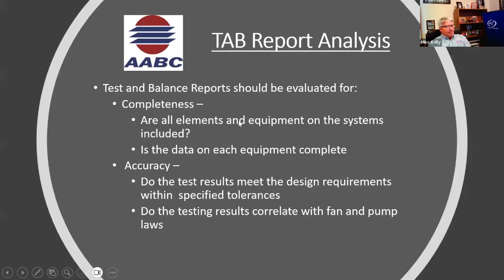All elements and equipment on the systems included. Is the data on each equipment complete? Test and balance reports should all be evaluated. Can you establish accuracy within a report? Do the test results meet the design requirements within specified tolerances? Do the testing results correlate with fan and pump loss? Those are things that you can look at to say, something's not jiving here.